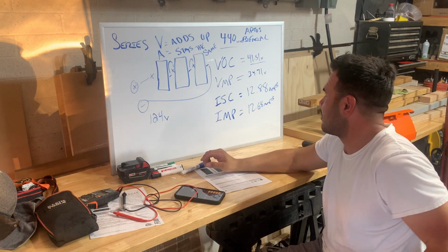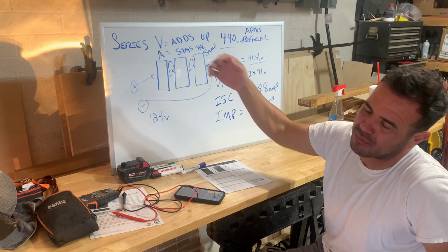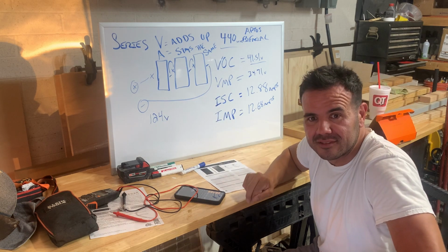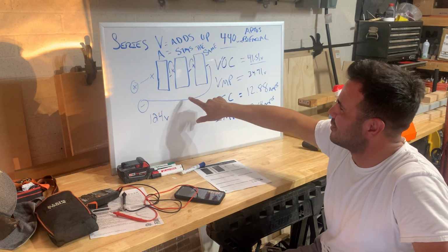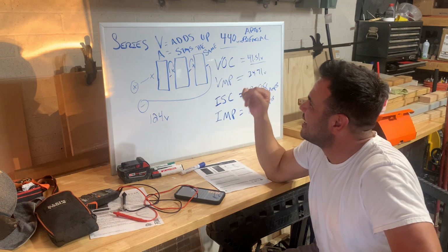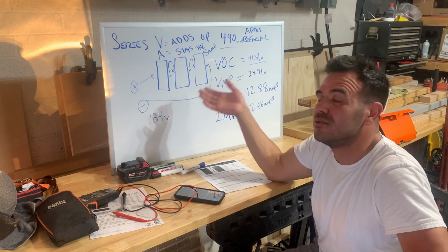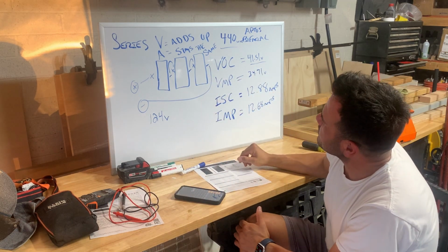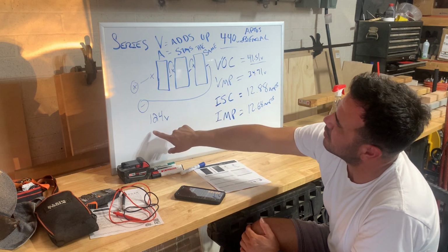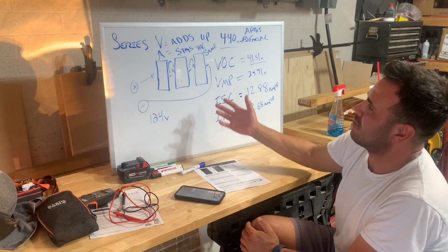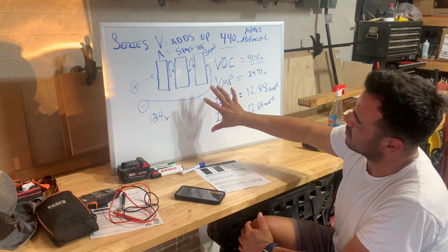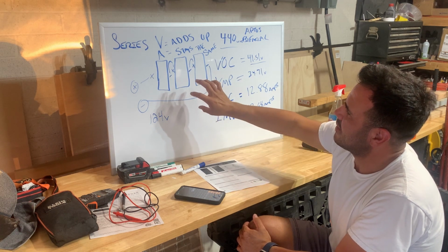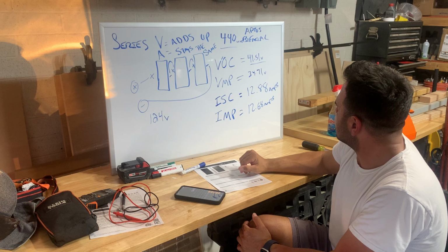It's probably not going to be exactly 124 volts, unless you have the perfect angle towards the sun and the perfect temperature, but you should get somewhere around 100 volts. If you're only reading 30 volts, that means there's something wrong. Either one of your solar panels is busted, or there's a connection that's not right, or something's backwards. But you can troubleshoot that yourself. If I hook up the voltmeter and I'm reading 105 volts, I can pretty safely assume that all my solar panels are working and the connections are right.